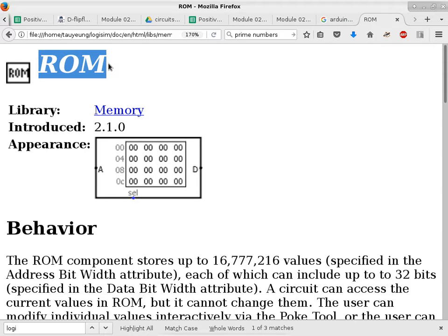It's an optical window. The erasable part uses UV, ultraviolet, to shine onto this portion, and then the UV light, now that part I never really got, but the UV light can reset the content of the ROM so they can be programmable again. It has a cycle limit of maybe a few hundred times, okay, and each time it takes about 15 minutes with intense UV in order to erase the chip. So it is slightly better because now, all the ROMs that are kind of old, outdated and whatnot, you can collect those back, erase all of those, and then reprogram those and use them again.